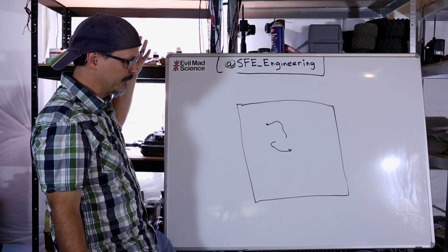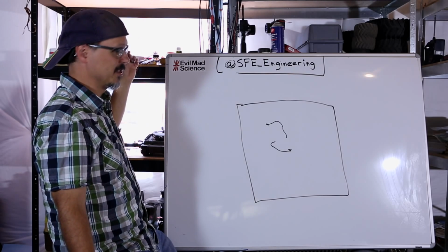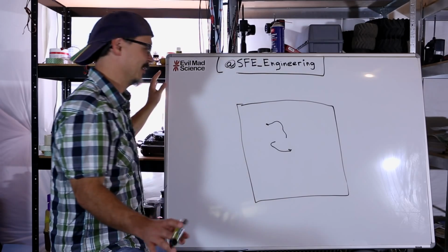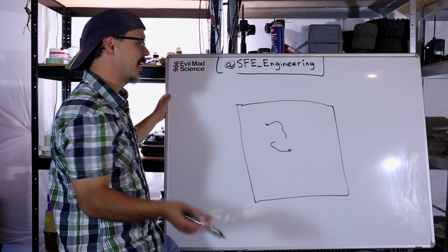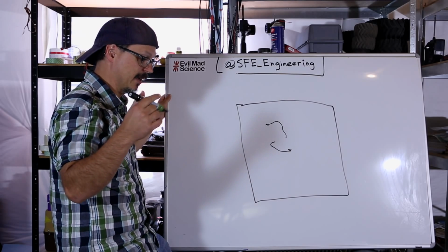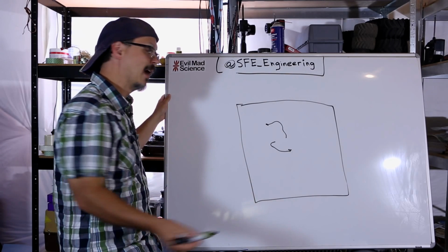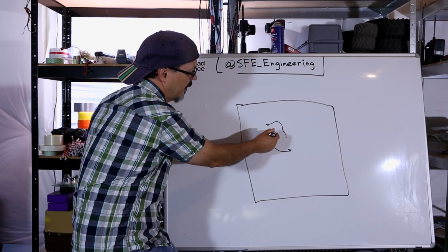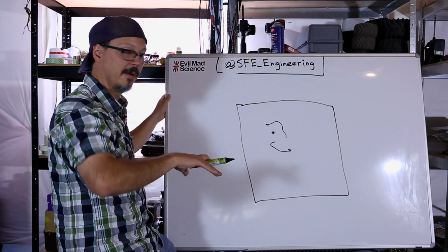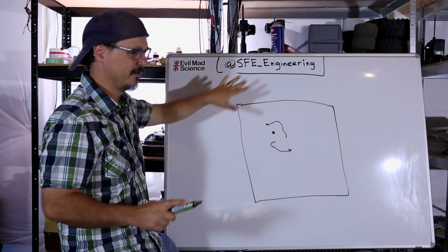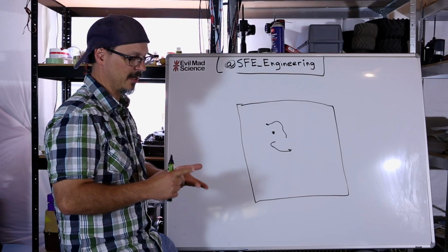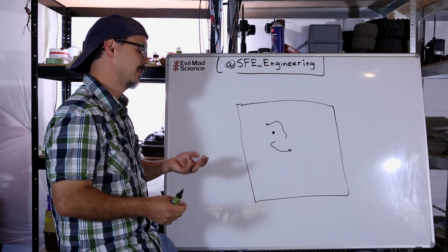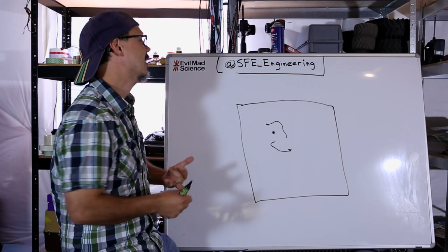And then the easiest thing to do, which is not necessarily the correct thing to do, but it's the easiest thing to do, is to lay a huge layer of copper all on the bottom. And every place in your circuit that has to go to ground, you just punch through with a via and you're at ground. You should be running your DRC all through this. DRC is design rule check, okay? It's going to tell you if you've got any dimensional problems. It's going to tell you if you've got any air wires.